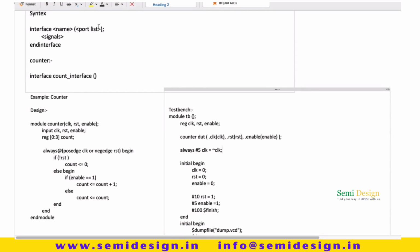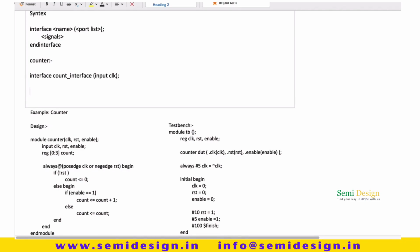So for the port list, I'll only write the input clock, which will come from the test bench, and another signal we will write over here. Here I am writing logic. In SystemVerilog, we usually write the data type as logic, because logic can be used in an assignment or a procedural block.